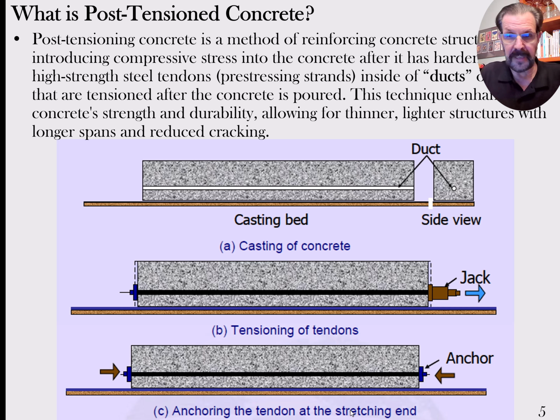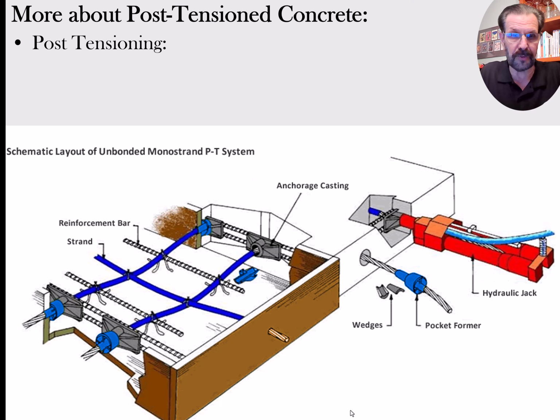Okay, so here's a diagram that kind of shows you the idea for post-tensioning, how we end up with this hardware that gets installed up against the form out in the field, and the pre-stressing strand, it might be drooped or it might be straight depending on what the needs are, across and chaired up to be in the middle of the concrete.